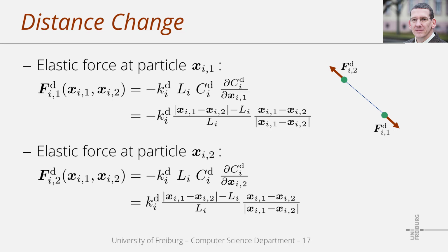As you can see, the forces act into the direction of the line between the particles, which corresponds to the gradient of the strain function, and which is the direction of the largest possible change that we can get for the strain. The other extreme case is a particle movement orthogonal to the line, where we would get a minimal change in the deformation, which is not our goal.